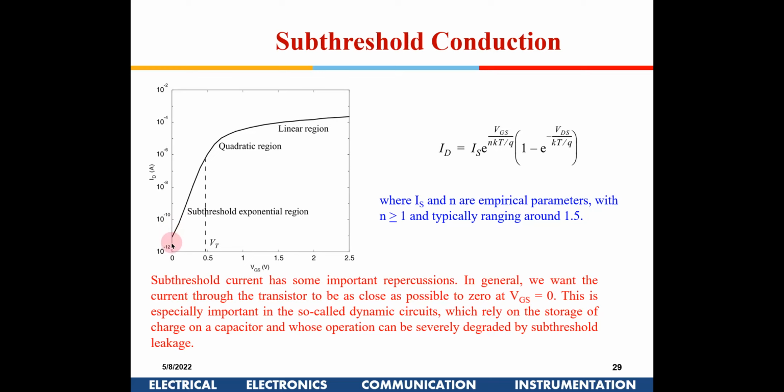If you see here, the leakage current is a few picoamperes, unlike in long channel devices, where it will be of the order of 10 to the power of minus 15. But for short channel devices, because of lower VT, the leakage currents are very high. Even when you give VDS equal to 0, you will find the leakage current is close to 10 to the power of minus 11, which is around 10 picoamperes. Even in simulation, I think you might have observed these kinds of off currents.